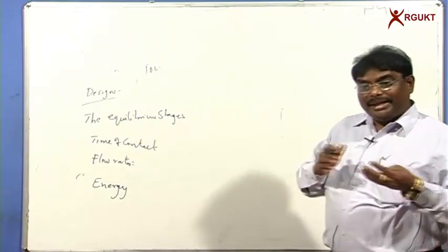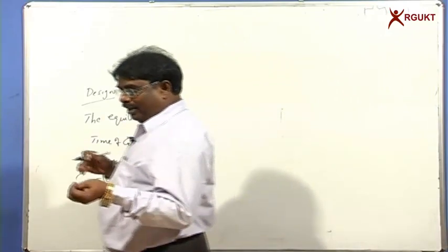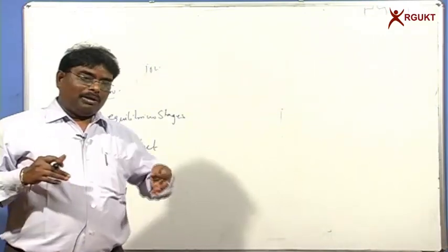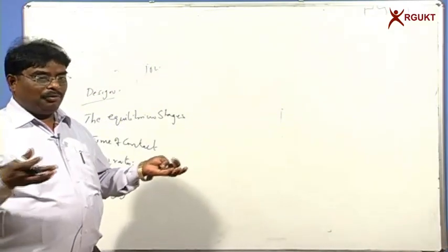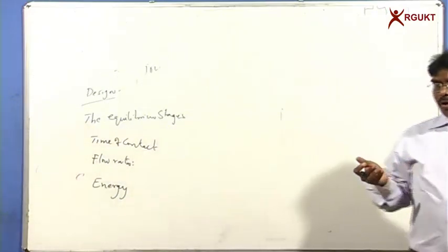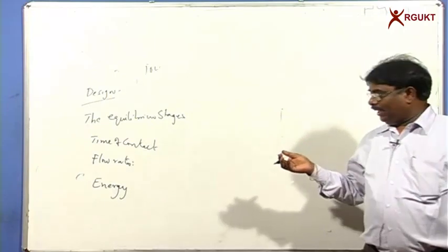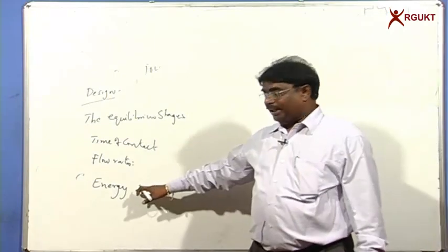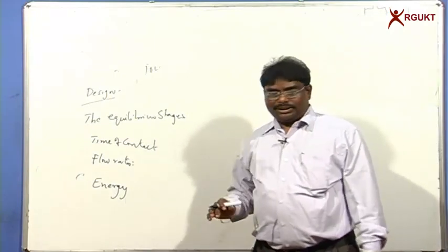One may be increasing the temperature. Maybe we have it at 30 degrees centigrade, and we may have to heat the solution up to 50 degrees centigrade without changing phase. Then we can use the equation of m Cp delta T, and we can calculate the energy requirement. That is what we call sensible heat.